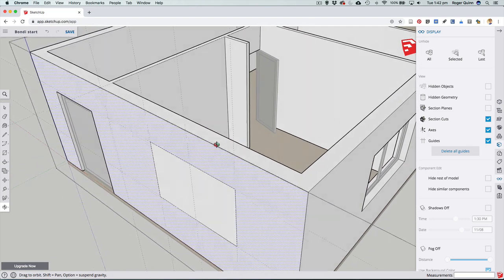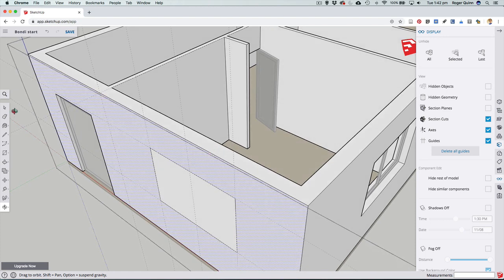So sometimes, for reasons that will remain unknown to the mystical world of SketchUp, it won't do that. So as I said, one way to absolutely ensure that it works is to just touch that inside edge that I can see up the top there. And there it is. Finally, another way to do that, of course, is just to know the depth that you're trying to cut through.